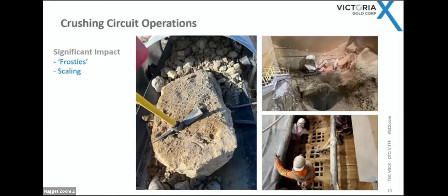Okay. So they fall off, they flake off, they get into feeders, they plug everything up. So it's absolutely critical to keep material moving. If you slow down and get these in the feeder, you basically have to choke off the whole feed, get in, scale it out manually by hand, then take it out.